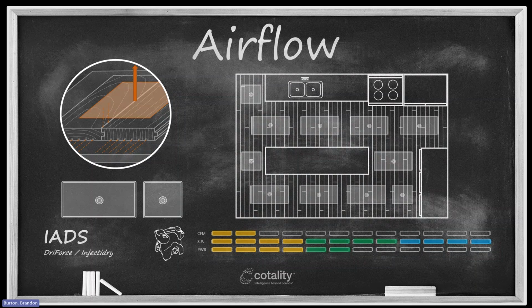The second thing that I want you to observe is that none of my mats are touching each other. If I place my mats so that these long edges are in contact with one another, that's the same as you putting your finger on the other end of the straw. In addition to the negative pressure that's pulling air up through the tongue and groove joints, I need to allow the positive atmospheric pressure to allow makeup air to go down through the tongue and groove joints between the mats.